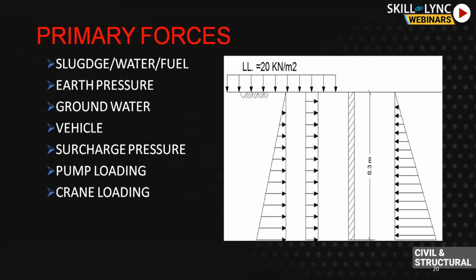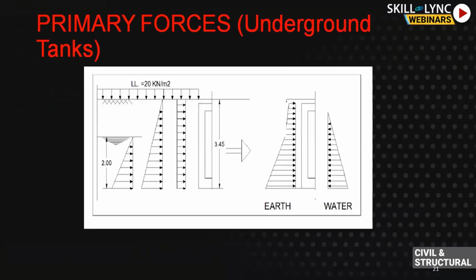On the left of this wall, the same wall is carrying earth pressure, and on the right groundwater pressure, and on the left surcharge pressure. Sometimes the vehicle is coming just on the top slab, so we have to consider truck loading. Sometimes there are other cranes, we have to consider those cranes. In the next picture, I'll show you again.